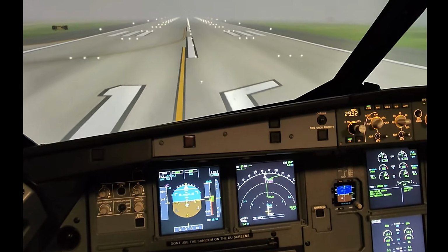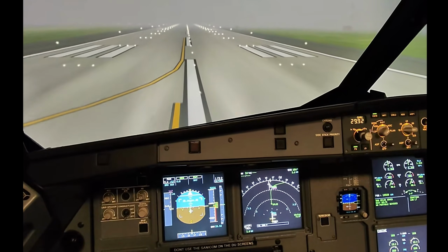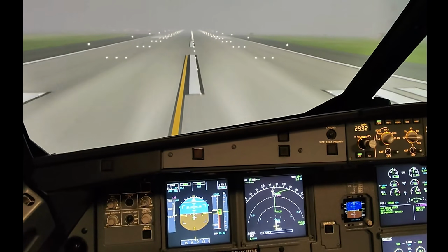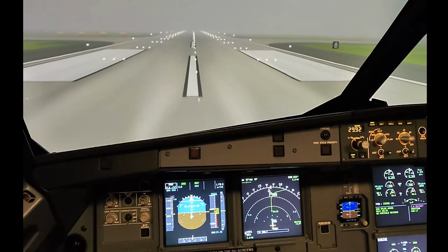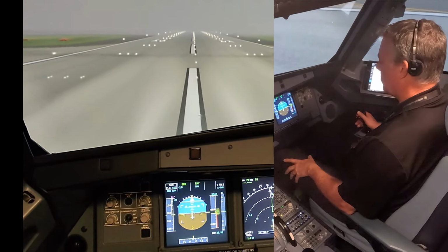Man flex, SRS runway, auto thrust blue. As with any takeoff, focus on maintaining runway centerline and do not anticipate the engine failure. Thrust set.